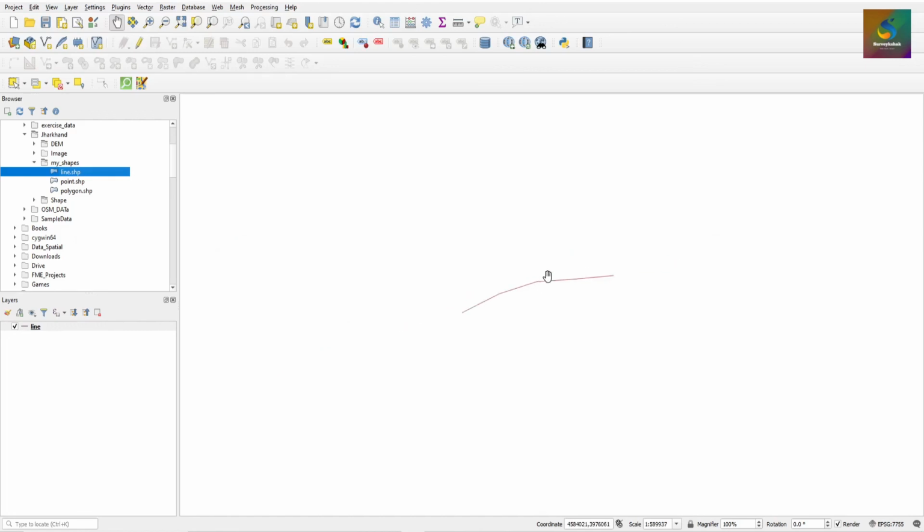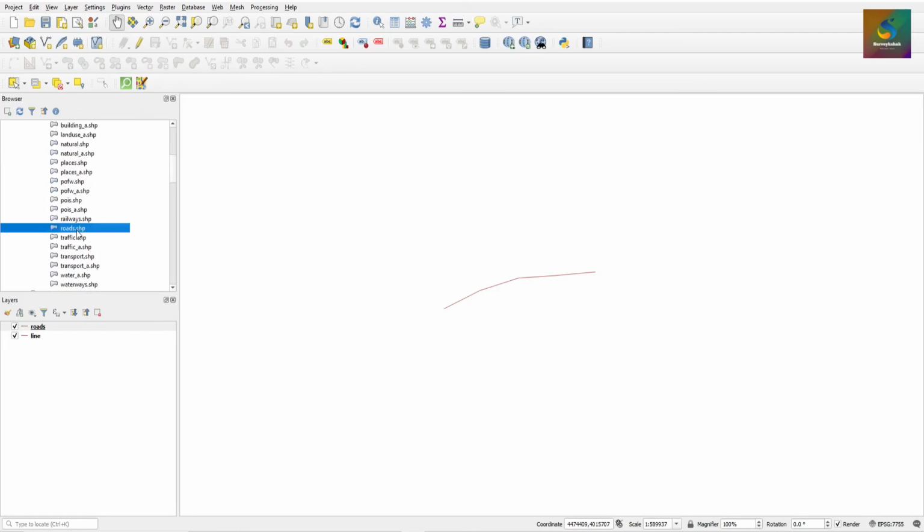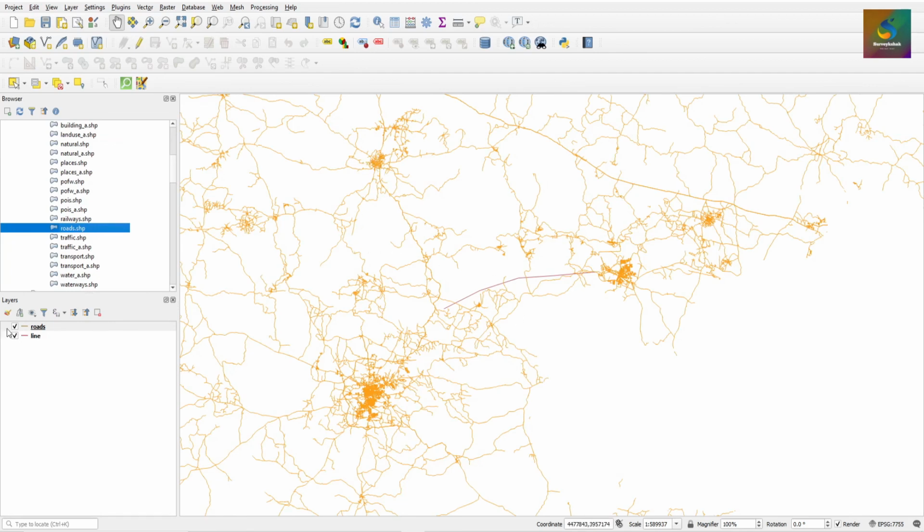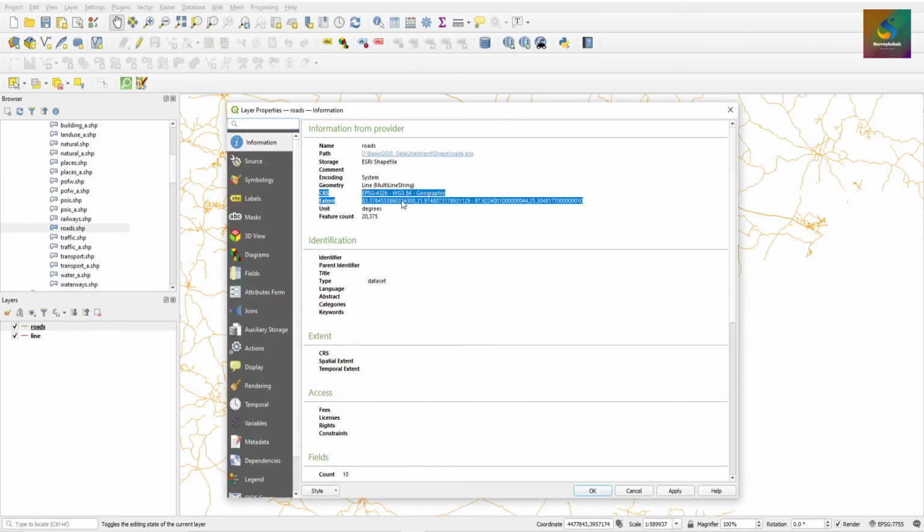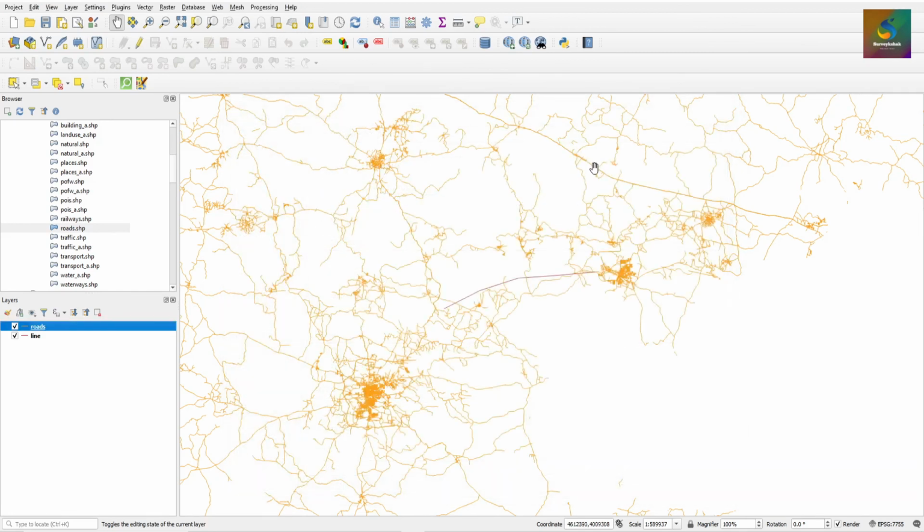So in a new project, the default projection system is 4326. As you load a layer of different projection, the project will transform to the loaded layer's projection. So now I load the layer of 4326 projection. You will see this is the layer. This layer will not lose its projection. This is 4326, but this layer automatically, on the fly, transforms to the projection 7755.